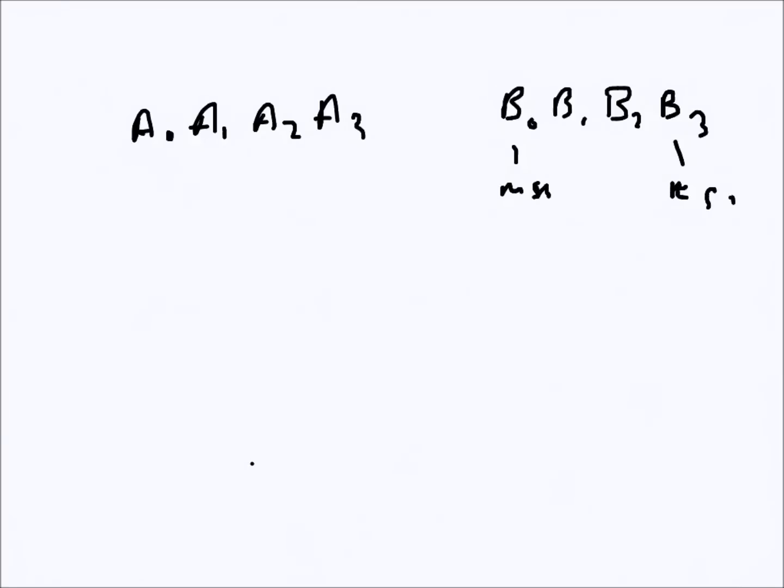So basically if I use 4 full adders, cascading them, I can have these 4 bit additions. I can get the 4 outputs. 4 sum outputs will be the 4 bit sum results, and the carry out of each one will carry on to the next stage, the higher significant stage.